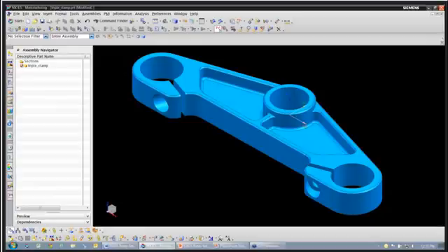So this means that after we create our operations, our tools, our tool holders, and save this file, then all of that manufacturing information will remain in this file, this main triple clamp file. We know that NX saves files as a .prt, whether it's an assembly, drawing, or even a manufacturing file. So if you want all of your manufacturing operations, tools, tool holders, all of that information to be in the same part file, you would probably want to use this method by just going to start manufacturing.